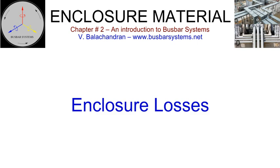Enclosure losses increase with the increase in the conductor current. Along with the conductor losses, enclosure losses contribute to the temperature rise of the enclosure, which is one of the constraints in the design of an enclosed busbar system. Certain types of enclosed busbar systems, such as continuous type isolated phase bus, generate losses due to intentionally induced circulating currents. These losses will be fed by the source to which the busbar system is connected.